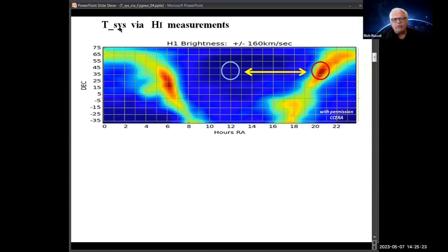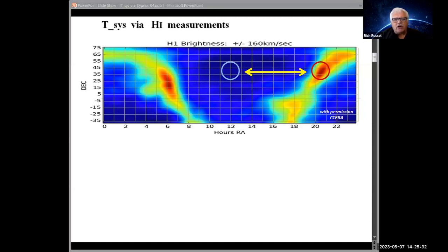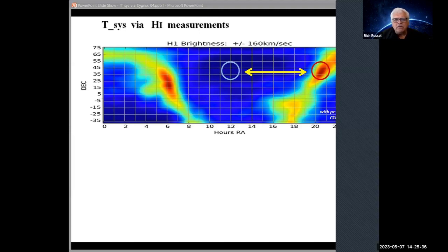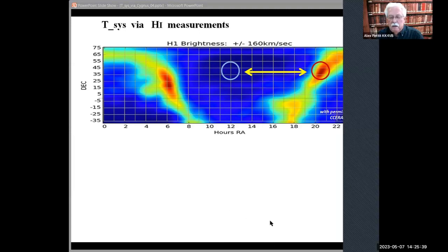What's the problem? I'm sorry. What the problem with that, Alex, is that you might be in the daylight on one observation and the darkness in the other, and it's just the temperature differences on all your equipment. I don't see a change. I ran a temperature characterization of the LNA last week. Put it in a little oven that I made, ran it from 75 to 120 degrees Fahrenheit, 1/10 of a degree dB change. Basically, it's stable.